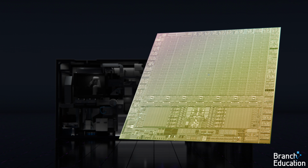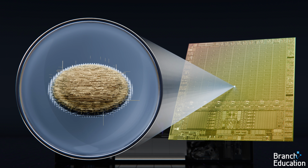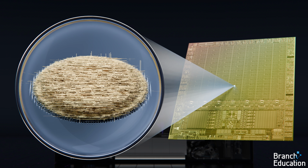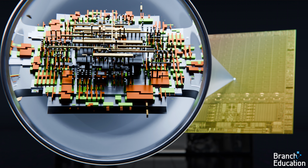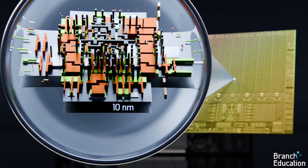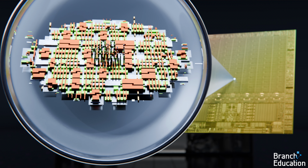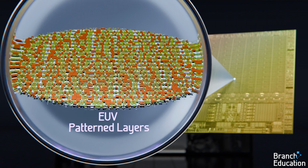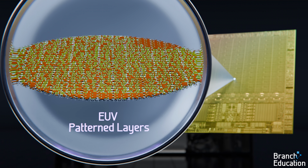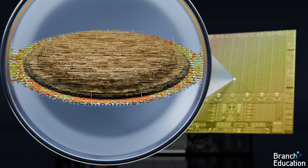When we zoom into a nanoscopic view of this microchip, we find a 3D maze of transistors and layers upon layers of wires with the smallest dimensions of the bottommost layers measuring around 10 nanometers or around 45 silicon atoms. Specifically, the EUV photolithography system typically patterns the lower layers with the smallest features, whereas other photolithography tools are used to pattern the higher layers.